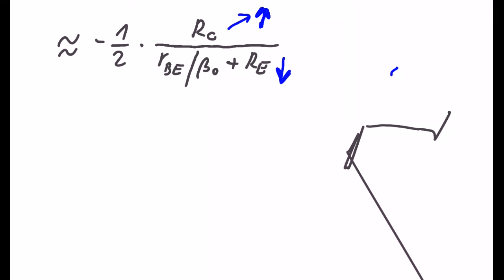So in case of paired transistors or transistors in an integrated circuit that have both equal characteristics, we can make RE to 0 ohms, so we can forget RE, and we see we have to use a very high RC, and the highest RC we can use is a current source. So in real circuits, RC is exchanged from a classic resistor to a current source.